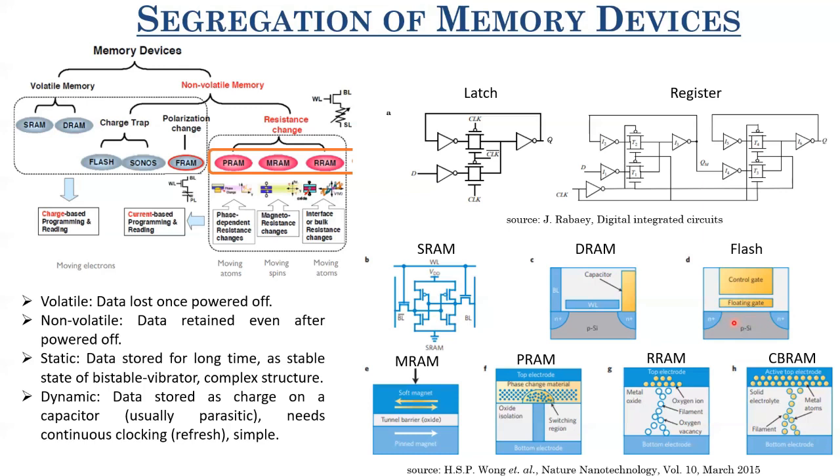And after 10 power 5 cycles, this storage layer or tunneling oxide layer becomes so poor that you won't be able to even operate it. So it works fine till 10 power 5 cycles of writing. After that, it degrades. That maximum number of cycles for which your device works is called endurance. We'll discuss that in later slides, but its endurance is low actually: the number of cycles for which this device can work properly.